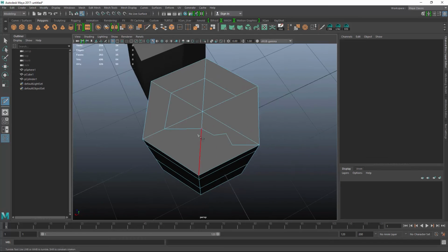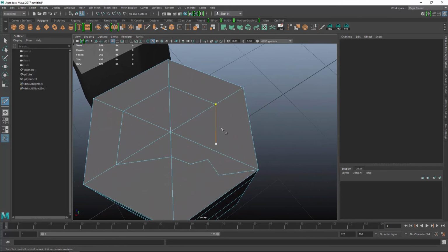So one of the other cool things this tool does is you can actually drag along this edge and hold control and shift, and it will do right angles. So if we go, you can see that this has created this right angle here. If we go this way, it creates here, or this way here, or a right angle from the point of origin. That's if you hold the control and shift key when drawing edges.